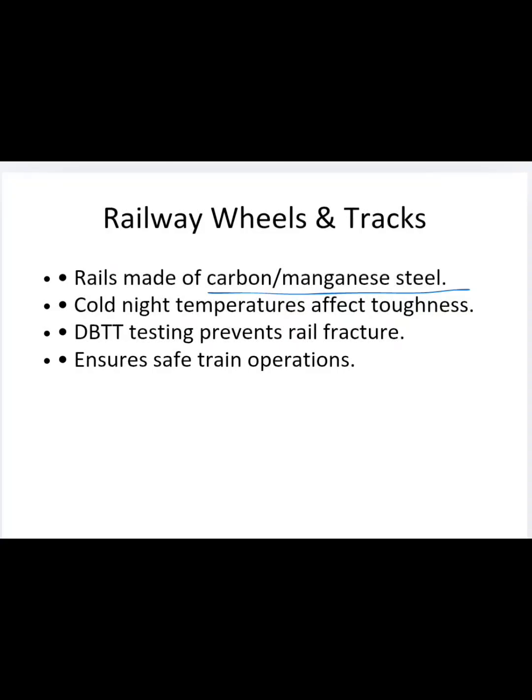If the temperature falls below the DBTT, the rails can become brittle and may crack under dynamic loads from trains. So DBTT testing prevents rail fracture.